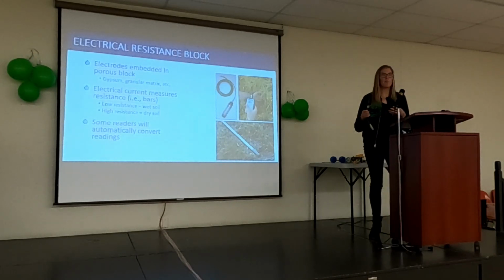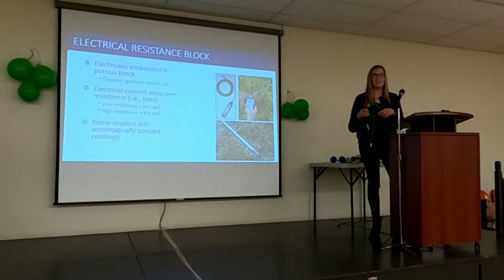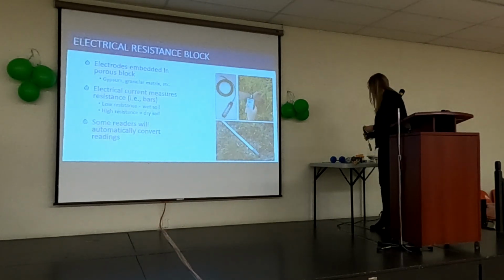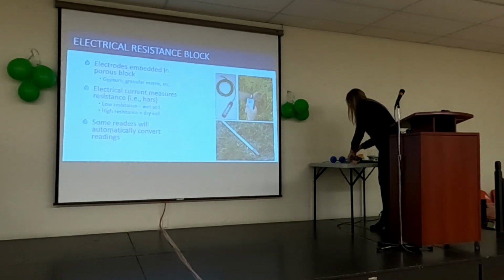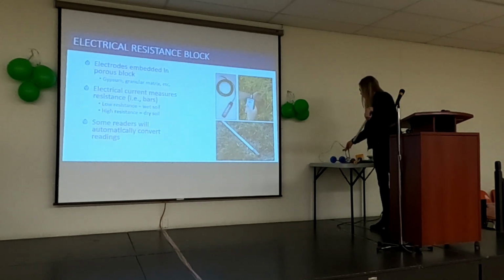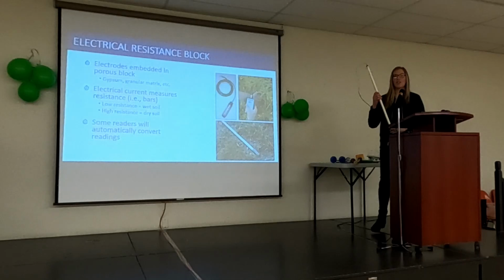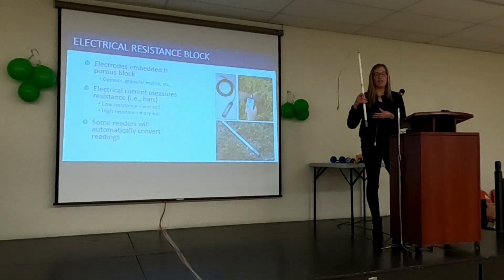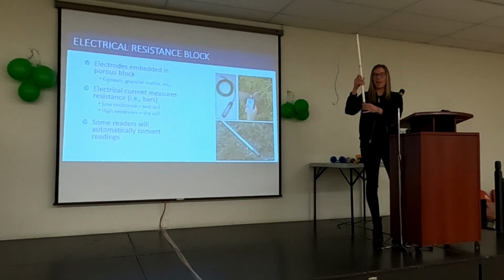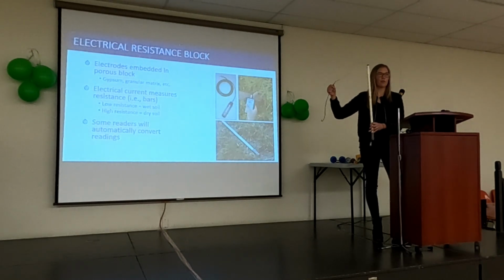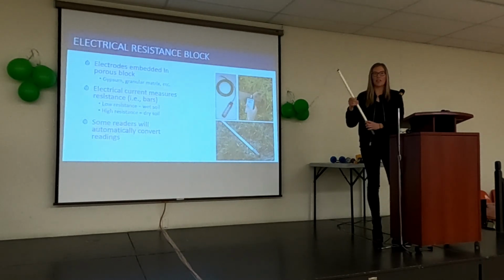So this is made by Waterware. This is a Watermark brand sensor. This is what you buy from the online store, wherever you're going to get it. And so what we do is we create this PVC vessel. You can see the granular matrix block is here, and then the lead wires are just strung through the PVC. Then we usually have a mark.